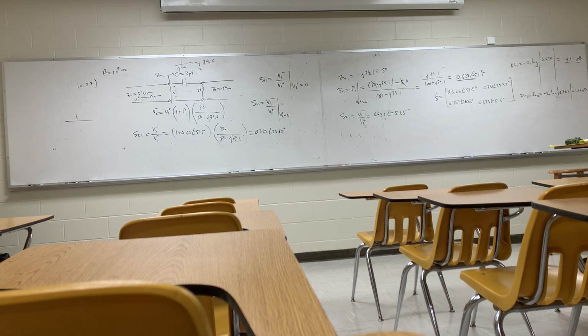What is the reflection coefficient, which would be S11? It's the impedance you're going into, infinity, minus the impedance you came from, Z0, over that impedance, infinity, plus Z0. Infinity over infinity is 1. S11 and S22 would be 1 for that one. So it's the opposite. Before, the first one we had was 0, 0, 1, 1. Now it's 1, 1, 0, 0. You can follow me on that?